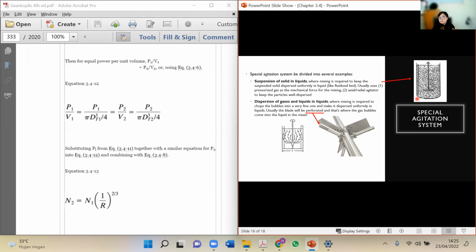The gas used in the sparger is pressurized gas, to act on the solid, which usually has higher density and stays at the bottom if we do not do anything. But after we do the sparging and also do the mixing, we hope that it can make the solids fluidize uniformly inside the tank.